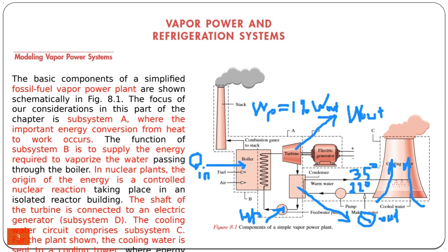The shape of the cooling tower is unique because, when you have a shape like this, as we will see in fluid mechanics, the air must accelerate. The accelerated air will have a lower pressure, and lower pressure will make the air move up. So there is no fan at the top, as you can see. Without any device, the air can move by itself from the bottom of the tower to the top only because of the shape of the tower.